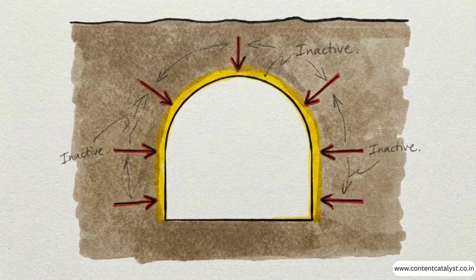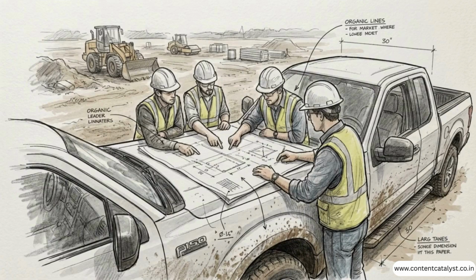This diagram illustrates the UI action required. Navigate to the activity frame, select the interior area of the tunnel, and set it to inactive. This mathematically simulates the physical excavation. The software's staging visualization tools immediately update. You can clearly see the empty void space where the earth was removed, leaving behind the newly exposed, unsupported edges of the surrounding soil. By isolating each chronological step of the excavation, we calculate exactly how the soil shifts and settles at each distinct phase. We identify the exact moment the ground becomes unstable, long before a physical crew starts digging.